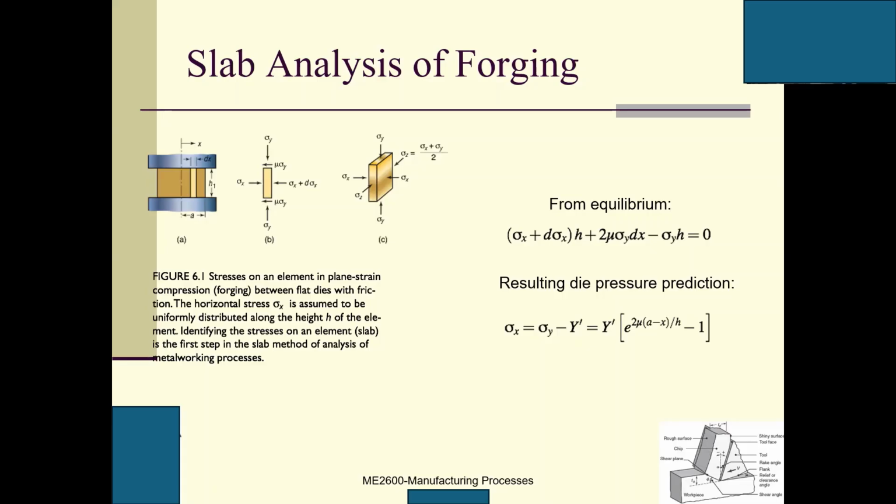This stress multiplied by h, also multiplied by the thickness, gives the cross-section area. The stress multiplied by the cross-section area equals the force. Because there is a thickness t here, here, and here, the t just cancels out. You understand, okay?